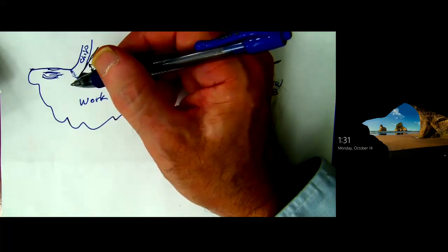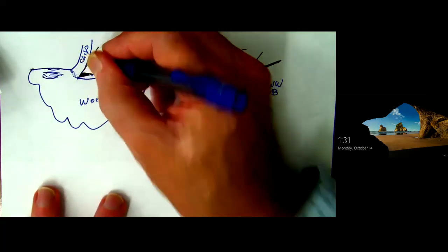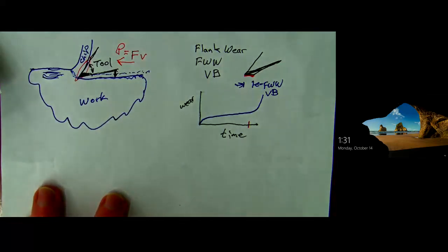So where is the other problem? The other problem is the friction on this surface. Remember, we're coating the tools to reduce the friction, among other things. That is sort of bad news. Actually, both are bad news as far as the tool's concerned. The shearing will cause the chip to be hot, and then I'm rubbing a hot chip with a big force on the surface.